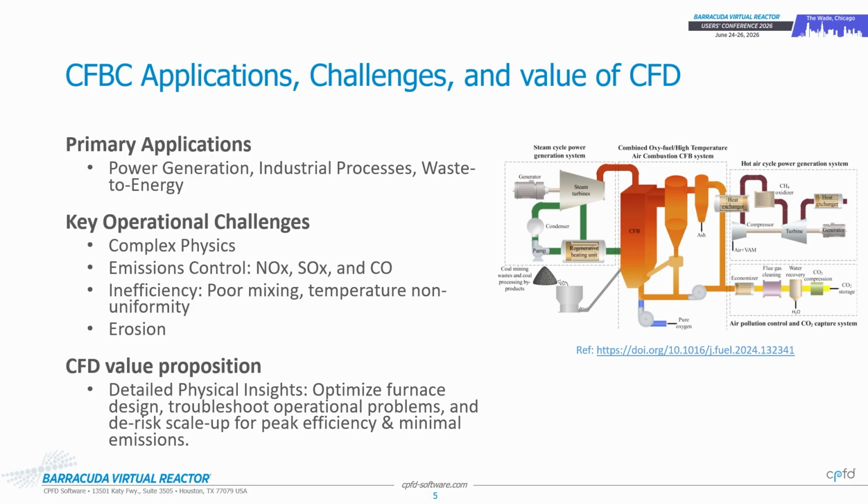You may experience, with poor design, inefficiency as a result of mixing or temperature non-uniformity, so you want to take care to ensure that the circulation is consistent in this system and we have good mixing behavior. In addition, anytime you have this high velocity solids entering through this furnace, you do have a risk of erosion potential.